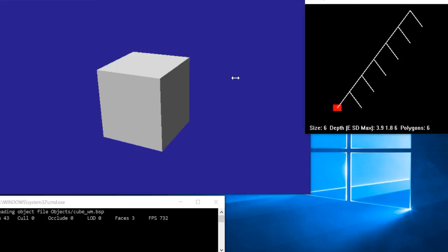You can draw inferences from that surface about the space, but you don't have an explicit representation of the space. The other thing that's different about BSP trees, as you saw in that, is that it gives you a solid representation as opposed to just a surface representation. And with that, we were able to do set operations and support the semantics of solids.